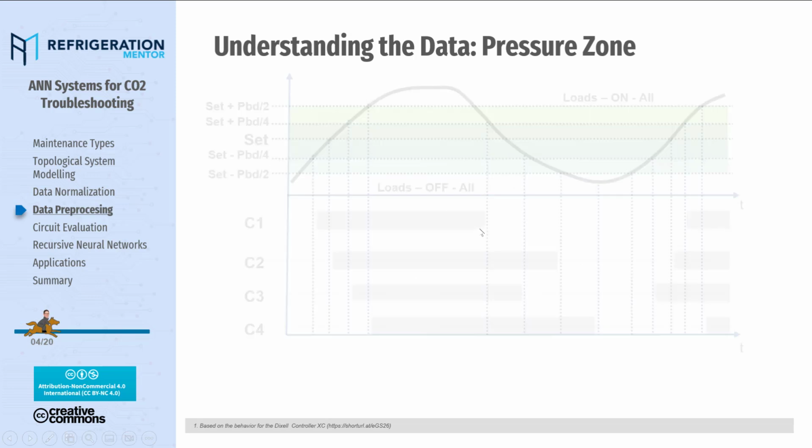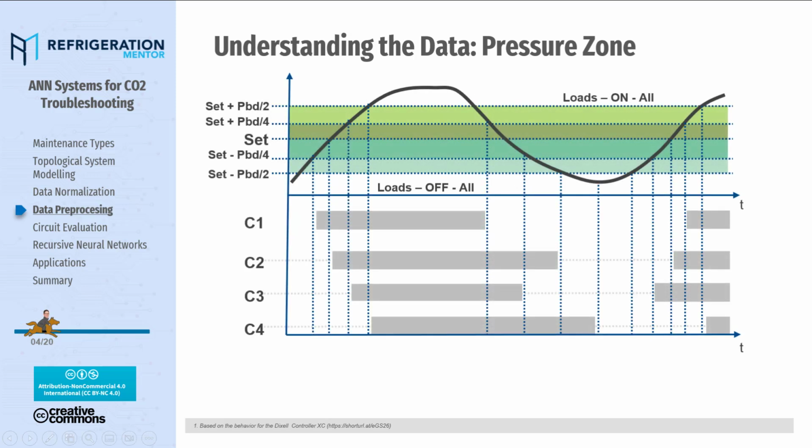Following this argument, we are going to start reviewing how pressure control works. The black line is the suction pressure for a specific suction group. There are two zones: one of activation, where the compressors are engaged, and the other when the pressure is too low, so we need to release the compressor load because the mass flow is too high according to the actual requirement.